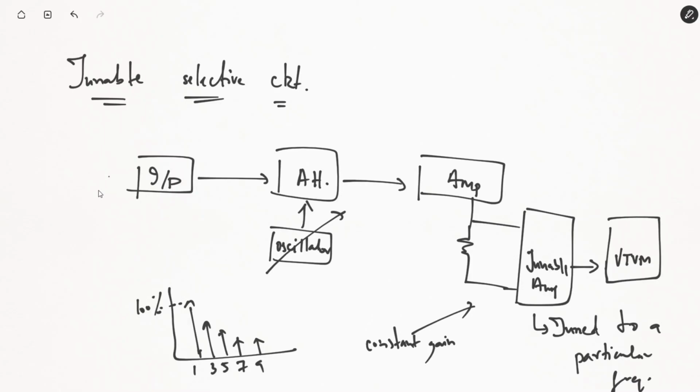And then the amplifier circuit is in that case set to a constant gain so that irrespective of whatever the frequency is, it will be amplified. So using this method, we can measure the magnitude of the fundamental frequency as well as all the lower order frequency components that have a significant magnitude as compared to the higher frequency components.